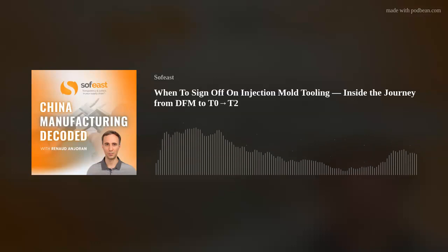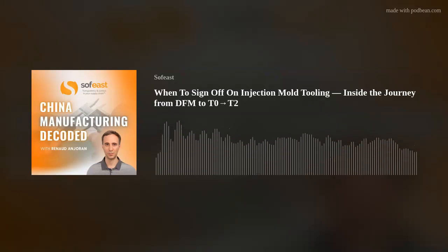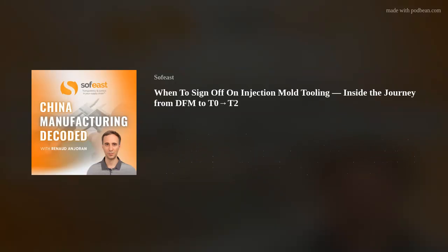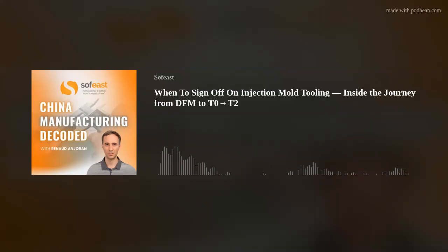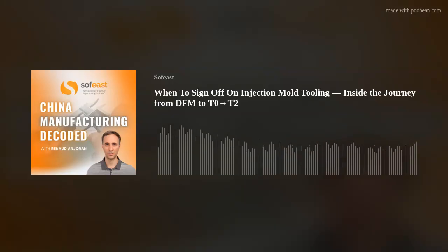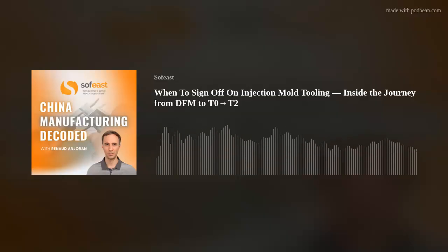Don't forget, it's really, really important that if you sign off a dimension that is outside of specification, you or get the designer to update the specification on the drawing. So this is really important because next time round, when it goes round for inspection, you've signed it off, but you didn't update the data. So the inspection team are checking against the original set of data points.